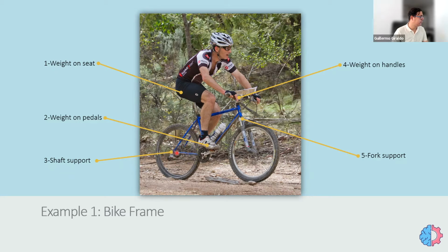So that will be our first boundary condition, right? Because we will model the wheel, the hoop, the shaft. That one we modeled, only the frame. So here we will have to apply our first boundary condition, right? Then the other support point is at the front, which is on the fork.